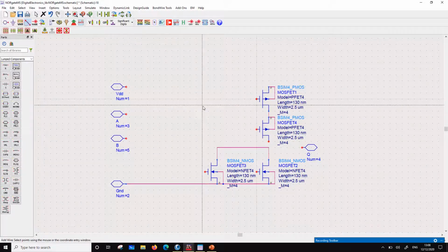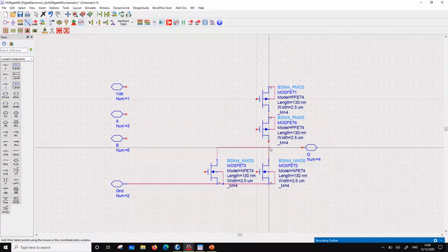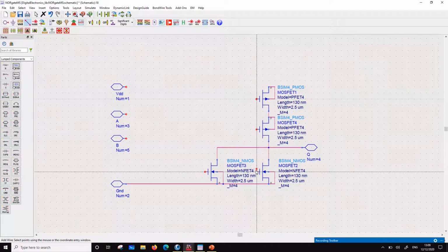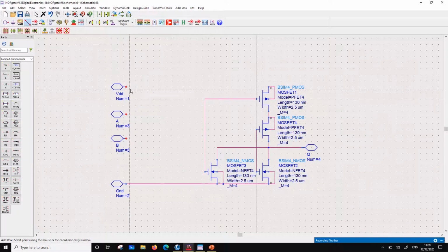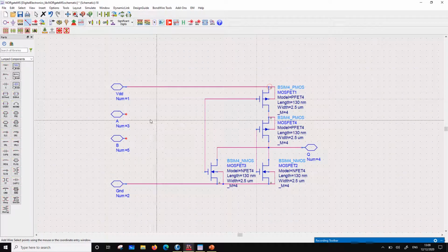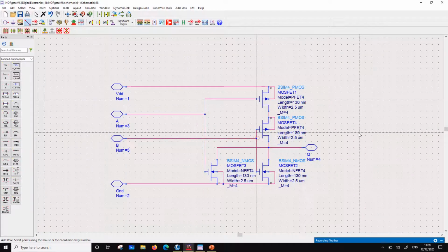So this is going to be a very quick turnaround, converting the gates from a NOT gate to a two-input NOR gate. And this is going to be one of the inputs, and this is going to be another of the inputs. So this is modified into a NOR gate, right? So all I had to do is, these are in stack 4 4, and this has become big, so that's fine. So I'm just gonna leave it as is.